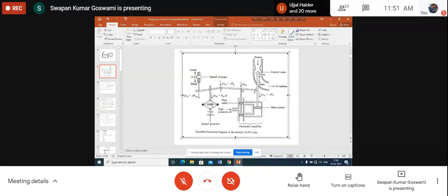So what decides the tension on the spring? It is decided by the speed of rotation of the fly balls. And who decides the speed of rotation of the fly balls? It is the speed of rotation of the synchronous generator, which decides the frequency of generation. When the frequency of generation is more, there will be more tension and the fly balls will move away from each other.